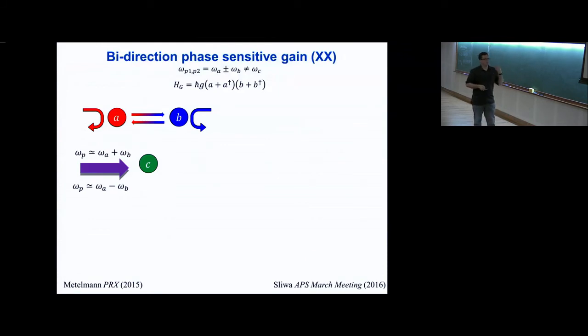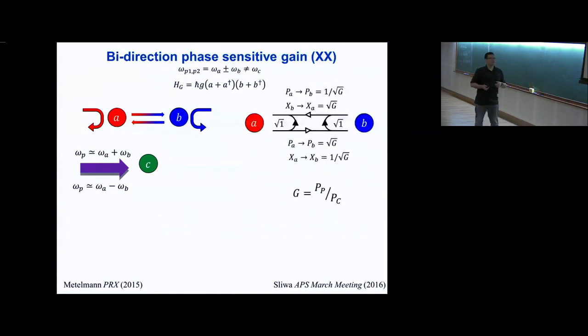And it turns out this is a really special basis proposed by Anja Metelmann of Aashish Clerk's group to build your multi-parametric devices on, because it has very different behavior than the standard 3-body term I showed you before. The first thing is that it is not amplifying in reflection anymore. It still has unity gain. We need to fix that with some more complications, but that's already a lot better. It's phase sensitive, which is interesting because basically the phase of this determines which quadratures get coupled together. So it's a phase sensitive amplifier in transmission, but it has really nice properties.